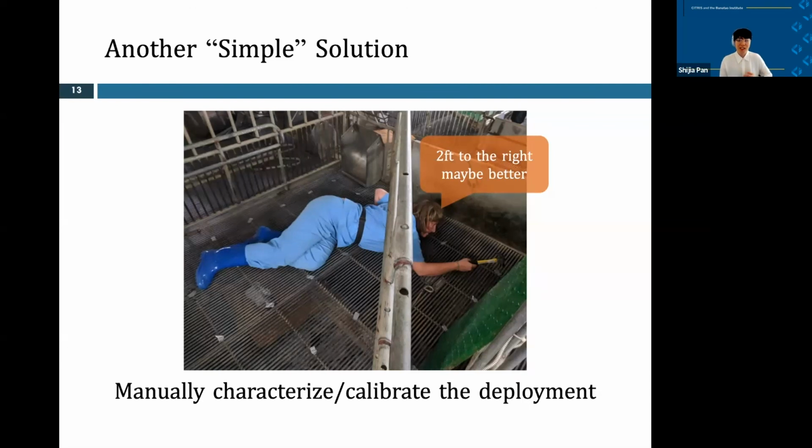So it really is a trade-off between how dynamic your environment is versus your sensor deployment, right? Imagine different types of loads could potentially impact your signal. Say furniture is a type of static load, while humans are also a type of more dynamic load. So if you see a lot of traffic or a lot of changes in the environment, then this automatic calibration is necessary over time.